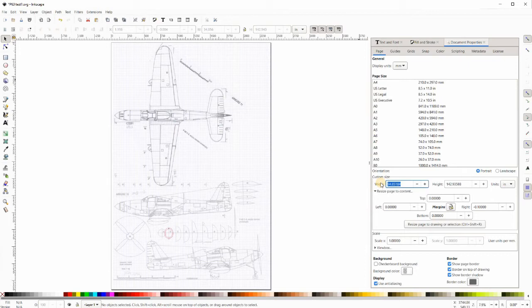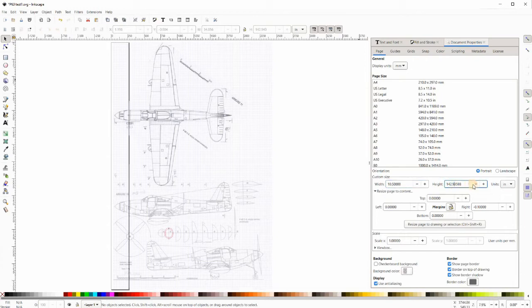The paper is 8.5 by 11, and usually there's a little bit of a border around the outside that you can't print on. So we're going to make this 10.5 by 8 to just leave a 1/4 inch all the way around. Just so that when we print it out, it actually is all printed and we don't miss anything on the edges. Now you can see we have our paper. This is our actual paper size.